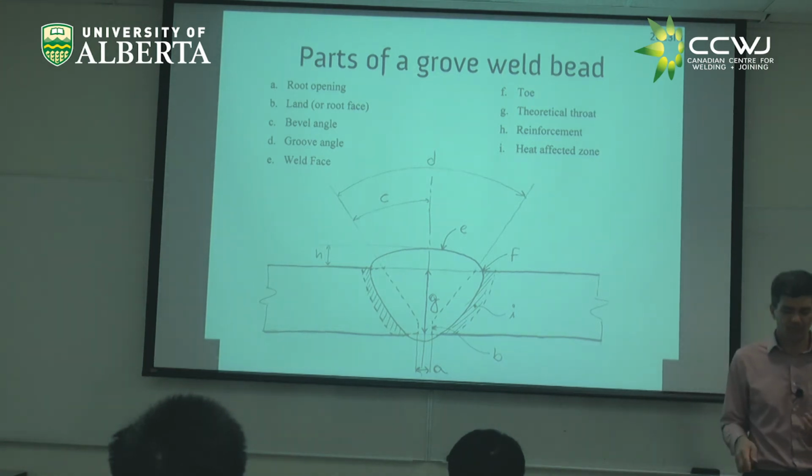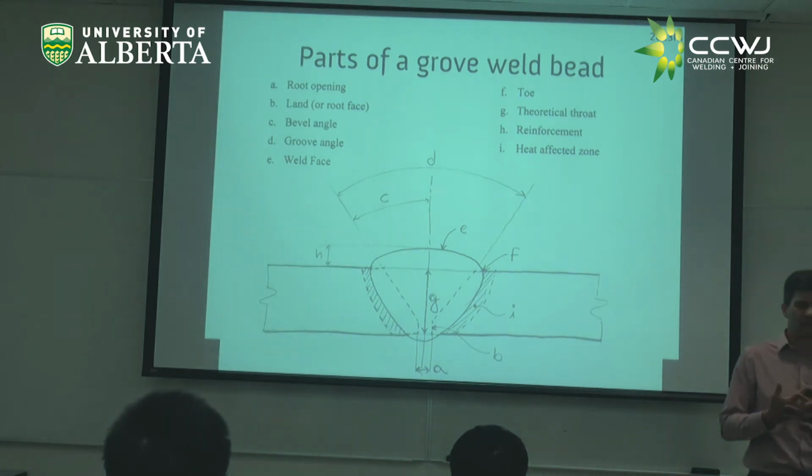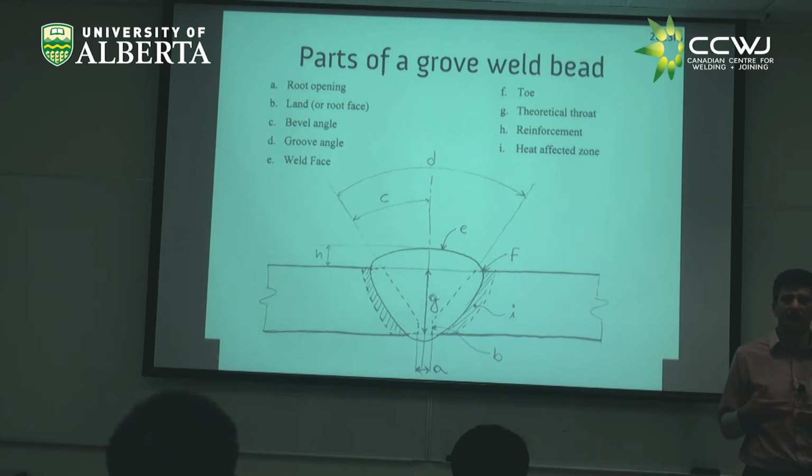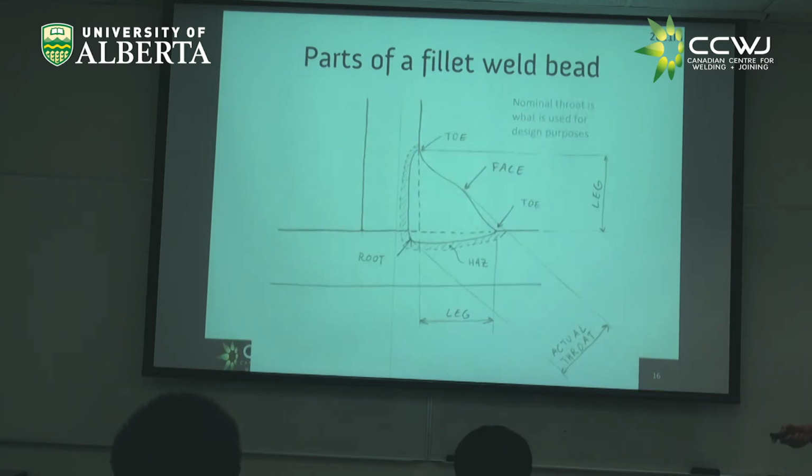So the US Navy was involved in the design of making super high blast resistant steels, right, in the 80s. These steels were awesome, but then you need to weld them. And when you weld them, you ruin the properties right around the weld, and they were not good. Conclusion, they have the awesome steels, they don't use the awesome steels because of welding, right? These are problems in which the heat-affected zone will not be kind to you.